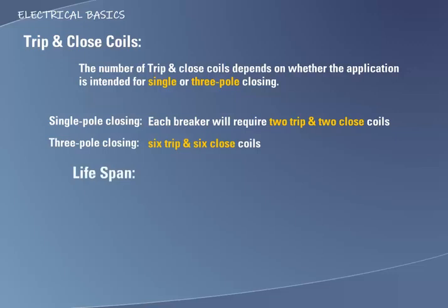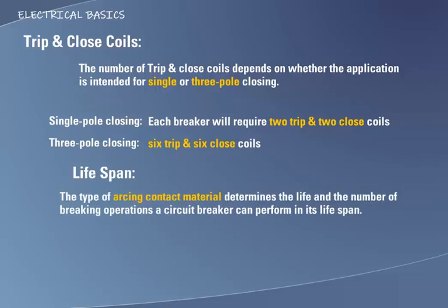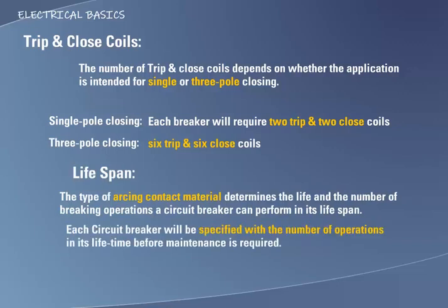Lifespan. The maintenance standards also play an important role in breaker selection. The type of arcing contact material determines the life and the number of breaking operations a circuit breaker can perform in its lifespan. Each circuit breaker, depending on the type and the materials used, will be specified with the number of breaker operations in its lifetime before it should be taken out of service.